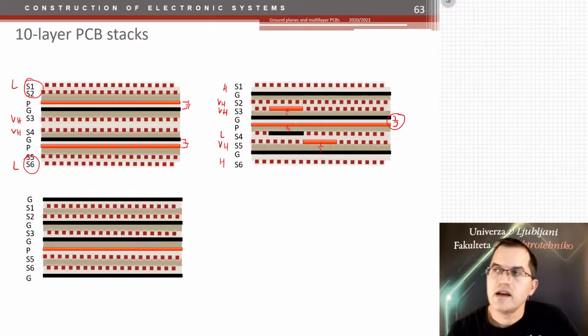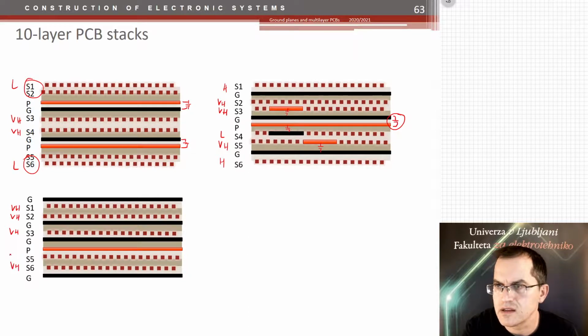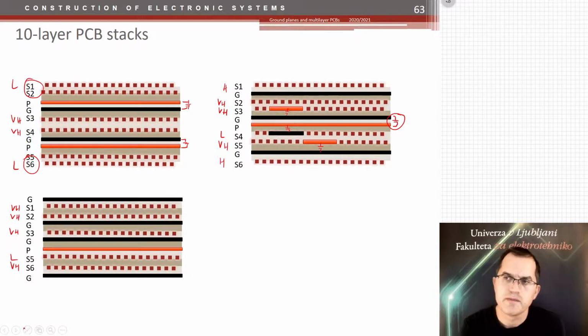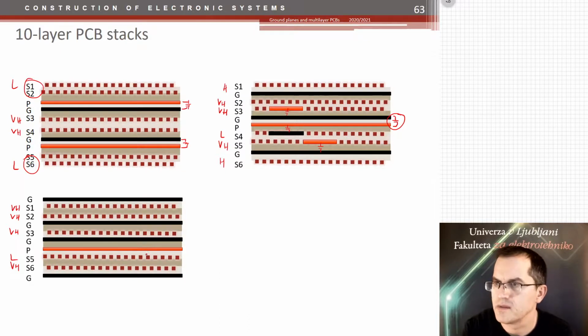Okay, that's another option when we just put the high-speed signals within. So now we have very high-speed signals all there, here, very high there, and let's say low speed on layer 5. Because here the tracks are close to the power plane.